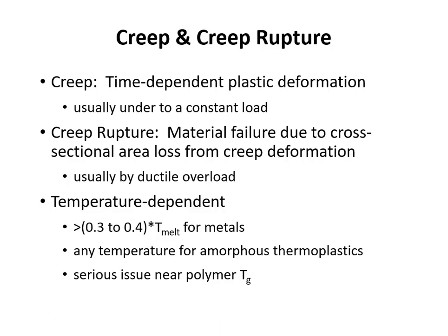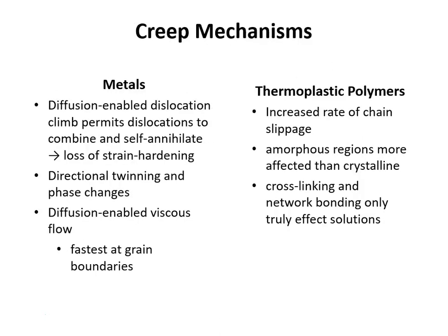In fact, not only is creep a bigger issue, it becomes far less predictable as we get anywhere near glass transition. So if you're designing with polymers, be very, very sure that you include the possibility or probability of time-dependent deformation, especially if you're near glass transition. And in fact, it's generally not a good idea to design polymers to be used anywhere even close to glass transition temperature just because of this. Just find something with a higher glass transition temperature.